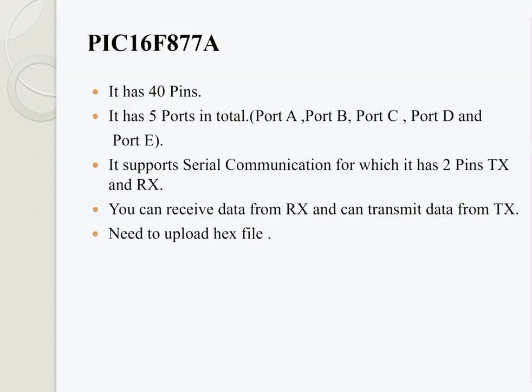The next is PIC16F877A. It has 40 pins. It has 5 ports in total: Port A, Port B, Port C, Port D, and Port E. It supports serial communication, for which it has 2 pins, that is transmitter and receiver. You can receive data from RX and transmit data from TX. You need to upload a hex file into the PIC16F877A.